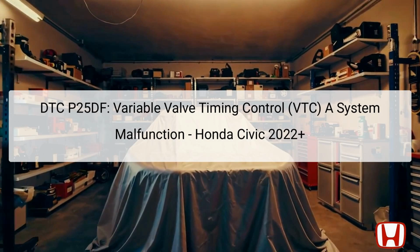The error code P25DF relates to a malfunction within the variable valve timing control (VTC) A system in the 2022 and newer Honda Civic models. This DTC is triggered when the powertrain control module (PCM) detects a significant phase difference between the intended phase command and the actual position of the intake camshaft.